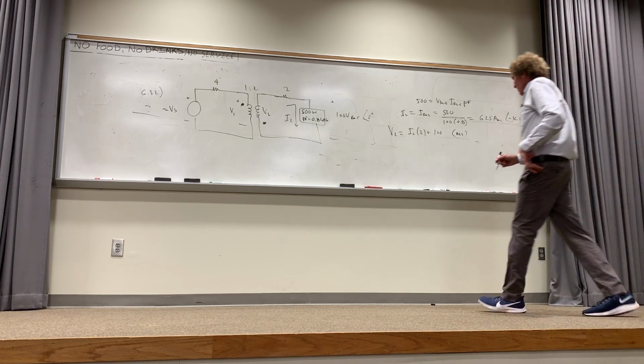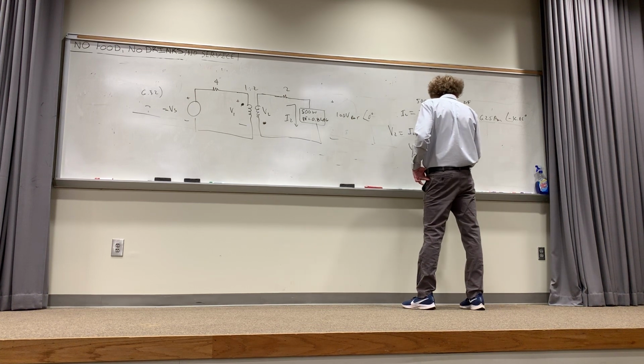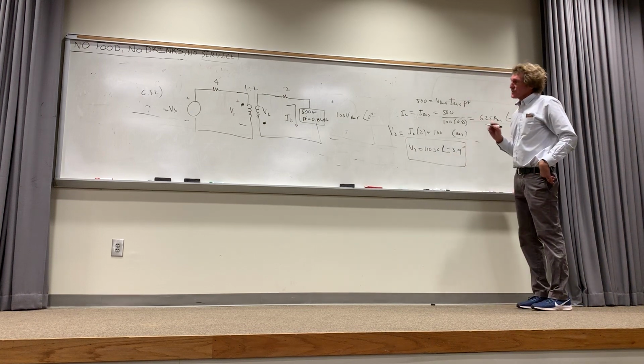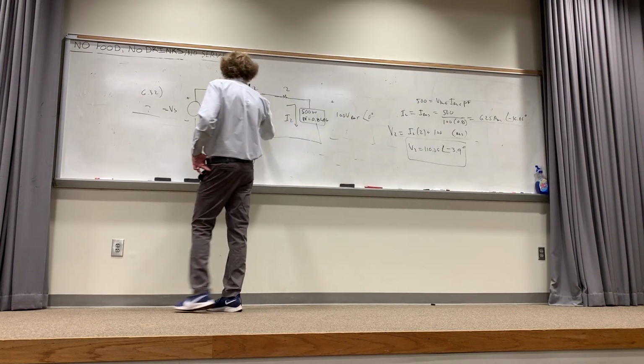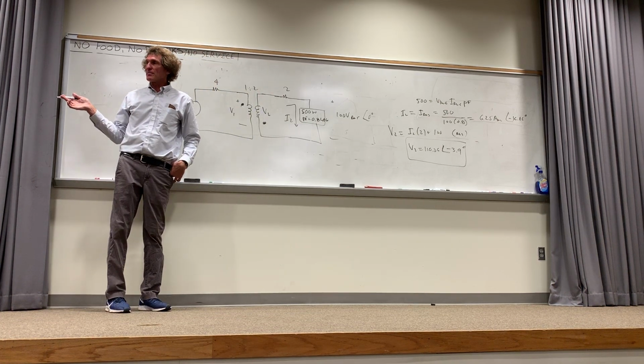110.26. All right, so V2 is 110.26 at what angle? Negative 3.9. Is that right? Yeah, 3.9 degrees, great. If that's V2, the turns ratio is 2 to 1. The primary has 1/2 the voltage of the secondary. Does everybody follow me in the way I'm talking about this?